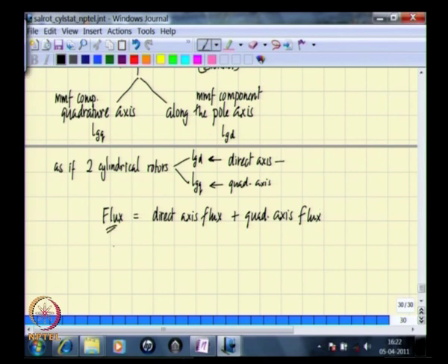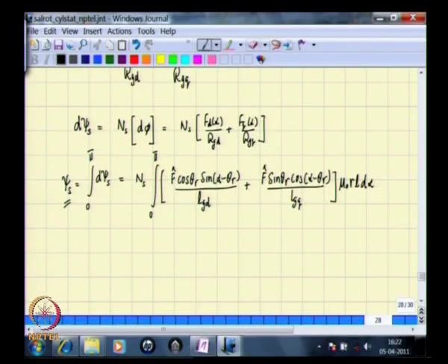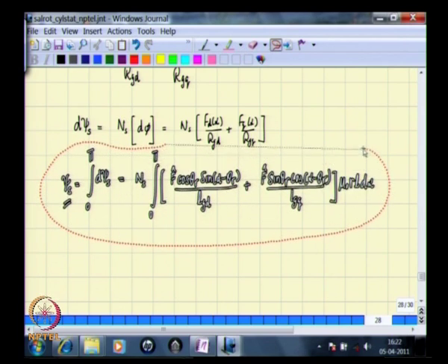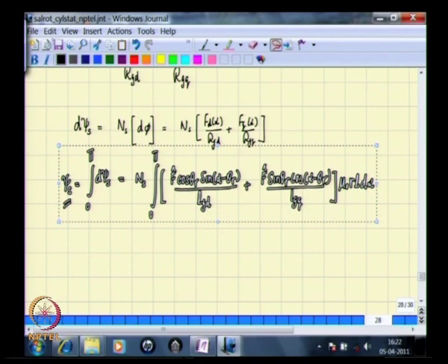This is at a particular area at a given angle along the circumference of the stator, and then if we want to find out the net flux linkage, you then integrate over the curved surface area of the stator, the inner circumference of the stator, and we had derived an expression for that which we will take from here. So, this was the expression derived in the last class, which we will copy and carry forward.